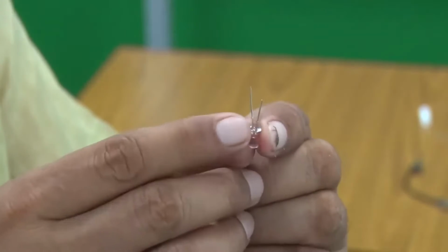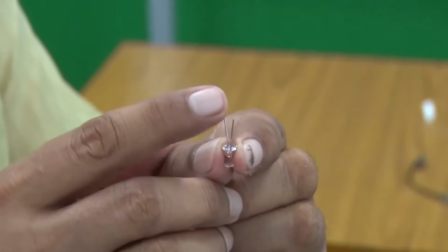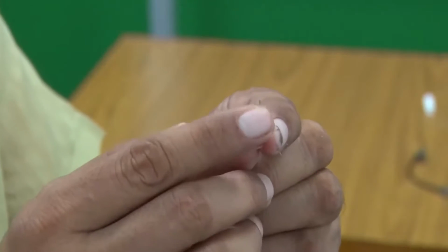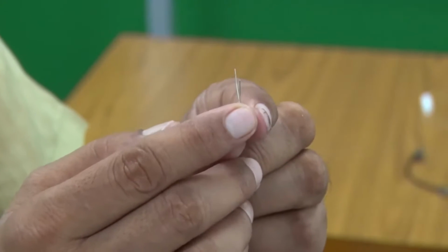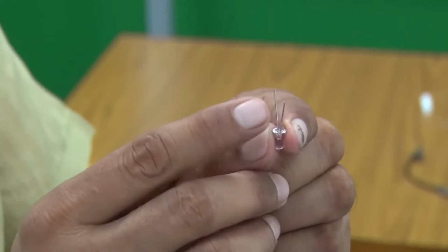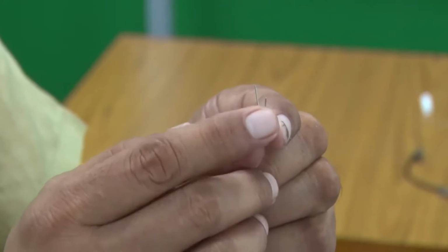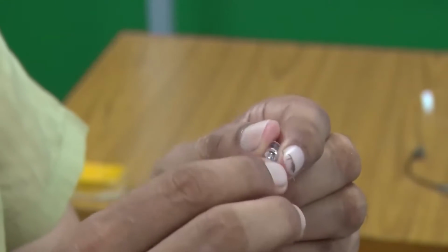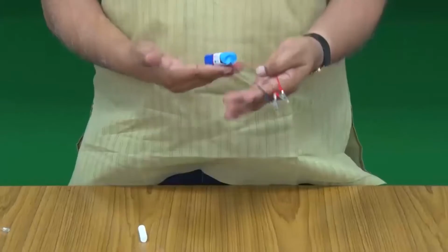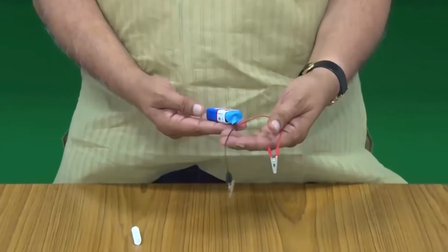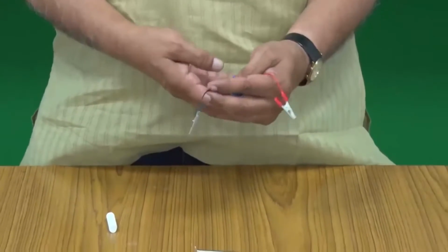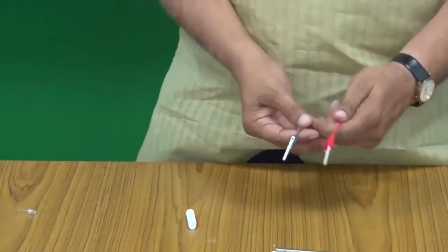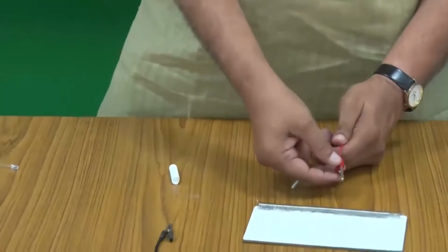This is to tell that the longer one is to be connected at the higher voltage side, and this to the lower voltage side for forward biasing. So, this is the P side and this is the N side. So, let us connect this, supply some voltage and see what happens. I have this 9 volt battery, but I cannot give this 9 volt on the LED, it will just blow. I will talk about that a little bit.